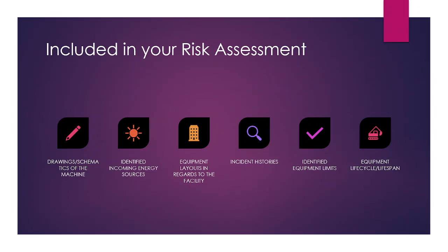We'd want to identify all sources of incoming power. So is it a mechanical force? Is it spring loaded in that mechanics? Is it hydraulic? Is there some kind of chemical transfer, heat transfer, any type of thing like that? We may need to consider that if it's a glue dispensing machine and it's a two-part glue mixture, those two glues mixing together, whether it be a static or dynamic mixing system, will produce some sort of heat that needs to be identified. So there you have a thermal type of energy, and obviously we have electrical energy that needs to be identified generally.